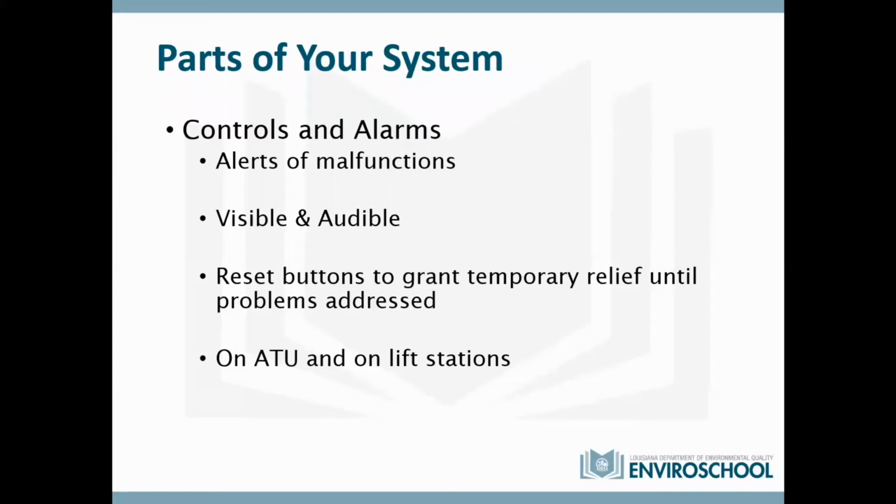You can have a system that's being clogged up. Some of these systems have a floating switch, kind of like the back of a toilet. When you flush your toilet, the back of it starts filling up and there's a float that goes up to a point and switches the water coming into the toilet off. Some of these systems have those in the actual tank itself. That way it knows when there's too much water going into it, which means there could be a clog on the other end and your system is backing up, and that would keep the system from backing up into your house or your business. At that point, you would need to figure out how to get the thing unclogged, snake it or whatnot, do some troubleshooting. So these things are here for a reason.